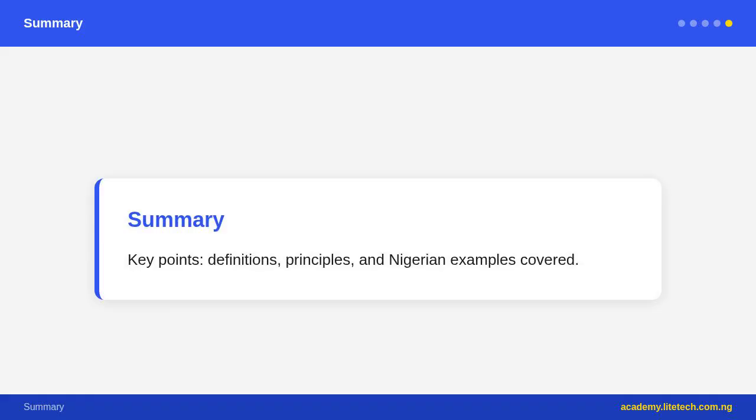Suspension bridge, deck hangs from cables slung over tall towers and anchored to ground. Cables carry load in tension, very economical for very long spans. Golden Gate Bridge. Cable stayed bridge, cables go directly from tower to deck.